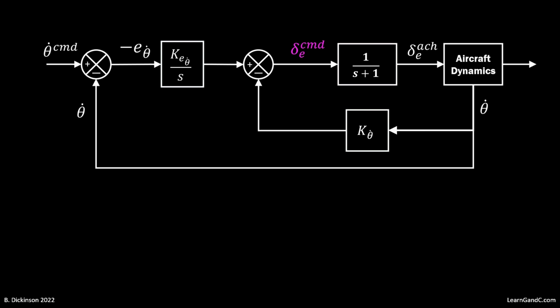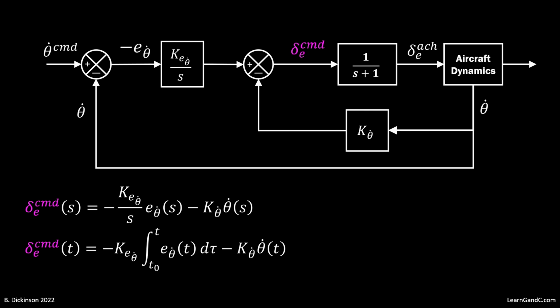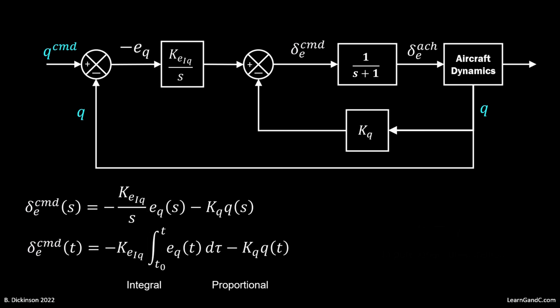This is a proportional integral control architecture, algebraically expressed in the frequency domain, also in the time domain. And finally, we note that the pitch rate Q is the time rate of change of the pitch angle, theta dot, when confined to the longitudinal plane. So going forward, we'll use pitch rate Q in our formulation.